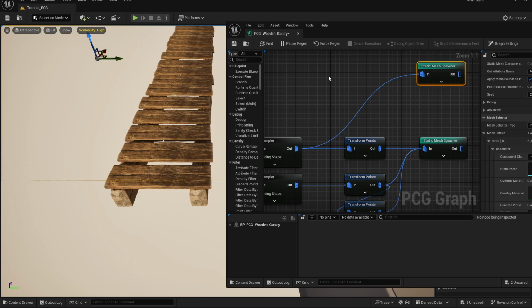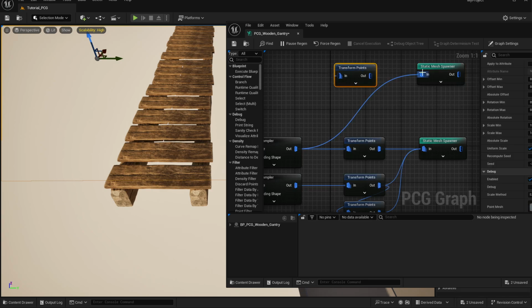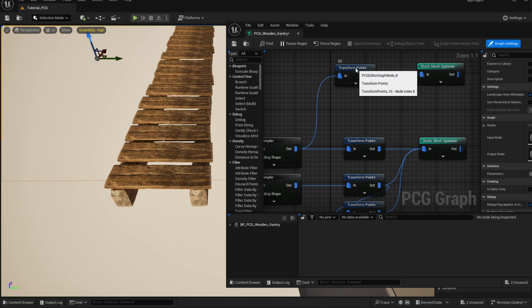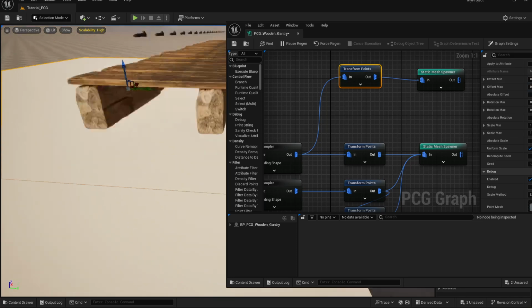Alright, well, we're going to need transform points, let's face it, aren't we? So I'll just type in transform points, because that's all we're using this time. We're basically using our artistic skills to do this. Now, if we mess around first with just the offset, just so that we can get it kind of above, there we go, should do it. And I think I need to put it on the Y actually, so I'll put it 20 above on the Y, just so it's kind of floating up here, yeah?